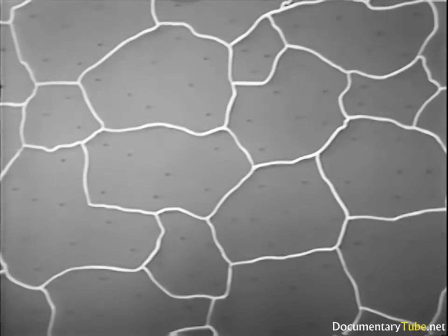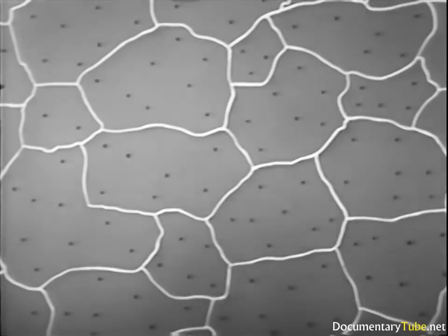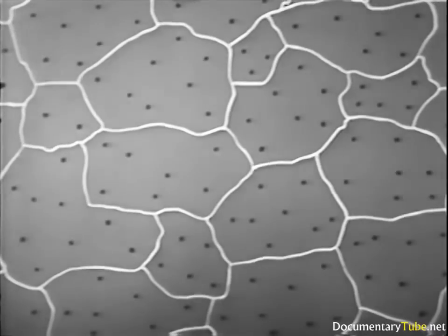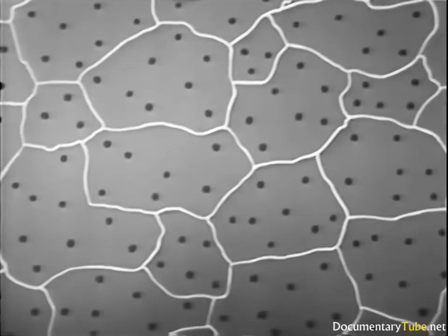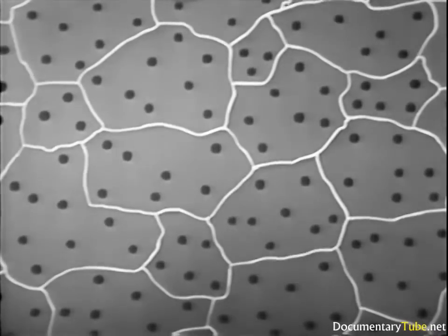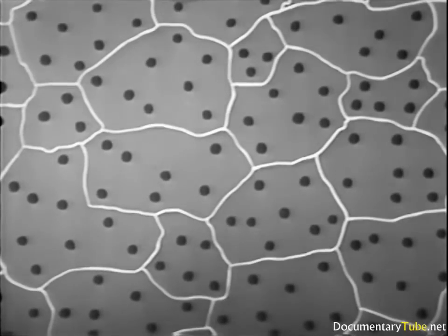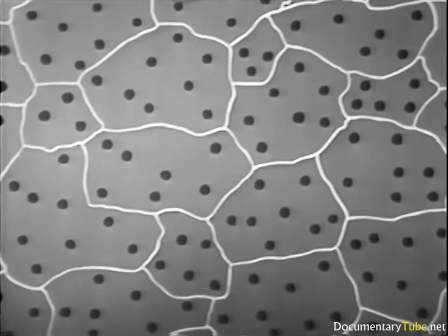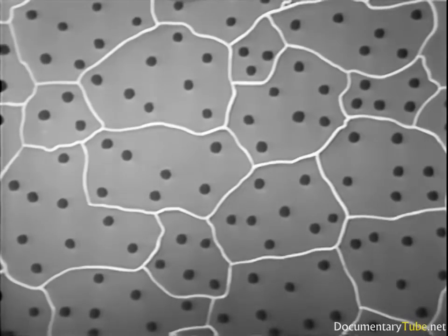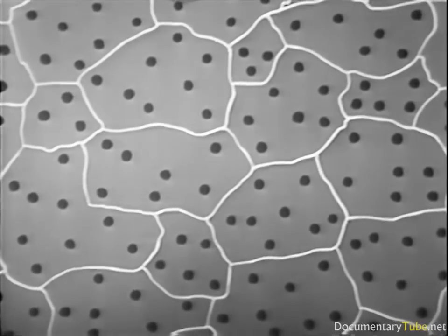Once more, the first internal change is that of recrystallization, removing the effects of any cold working that may have been present. But this time, in the second change, most of the CuAl2 is precipitated out of solution in the form of coarse particles. The metal is now in the annealed or soft condition.